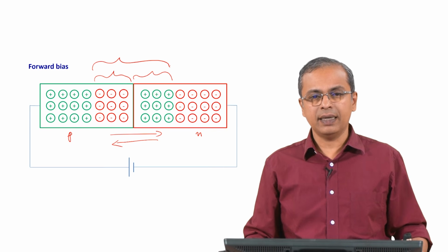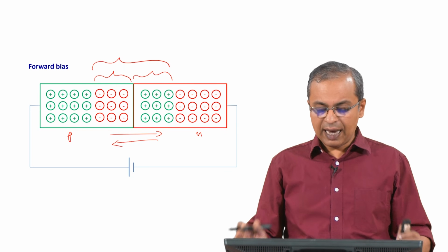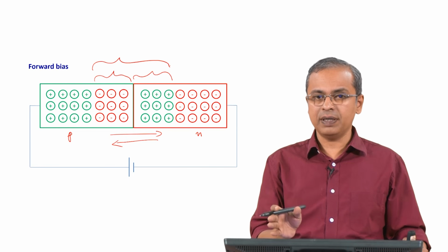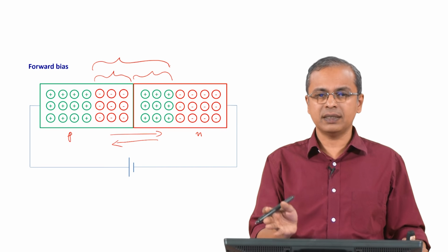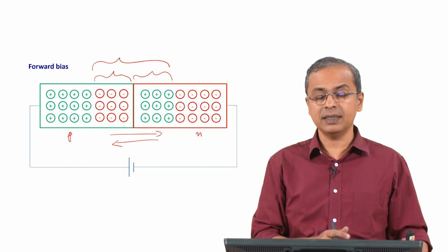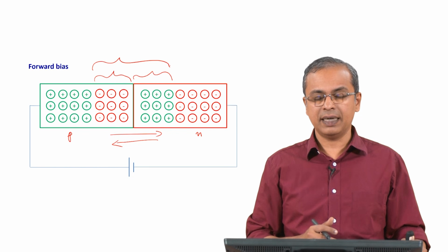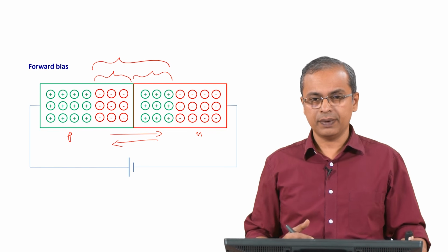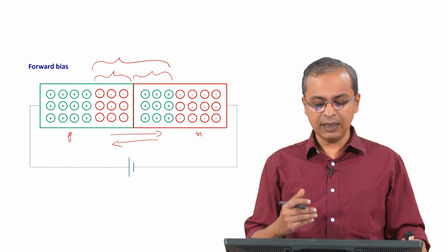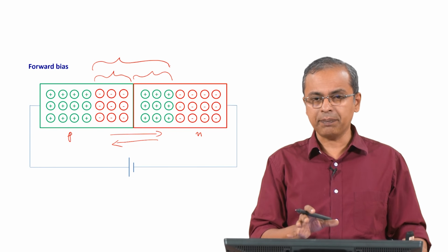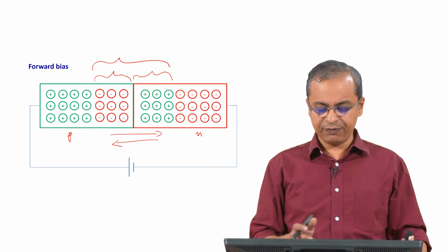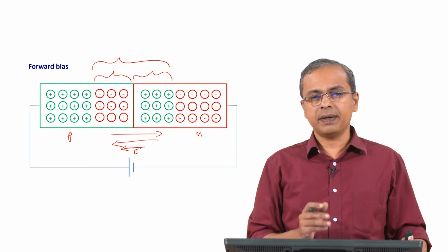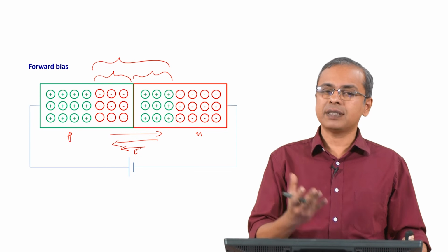So, this is how the build up is there, and having put this together, you can attach a battery to it. So, now clearly because you have put charge on either side of it, I mean not put, it has automatically redistributed its charge and created this space charge region. So, there is an inbuilt potential that has been created. You can put a potential outside of the sample which can counteract this potential or build on this potential. Okay. So, this potential that builds inside this sample, or the field, which would actually be from the positive to the negative, so the E field would be this way. So, this potential is preventing further flow of charge, right.